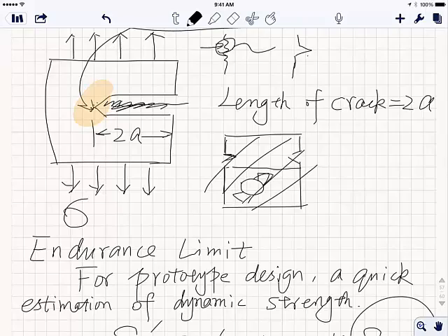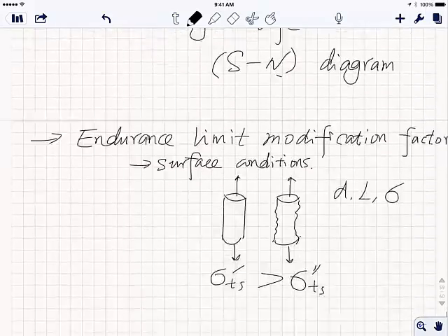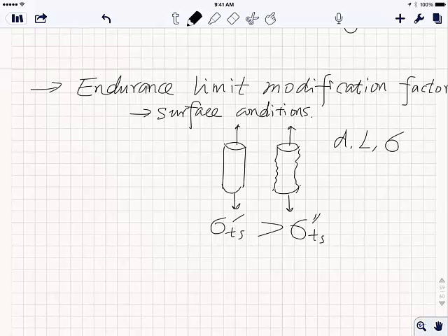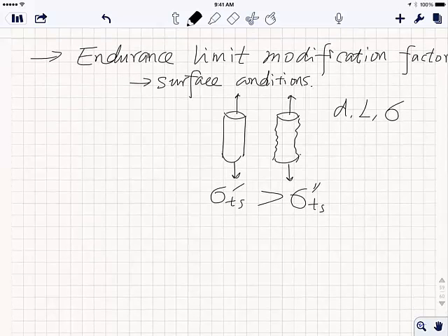That's why whenever you have a mechanical system, you're trying to do a very good job in polishing, make sure that it's smooth. There's a good surface roughness, right? The roughness number is low, in other words. Okay, so surface condition matters, for a shaft or for any component under dynamic loading. Especially if you have local stress concentration under dynamic loading, it's going to exaggerate it, because we know dynamic loading has less strength compared to static, right? Okay, so surface condition matters.